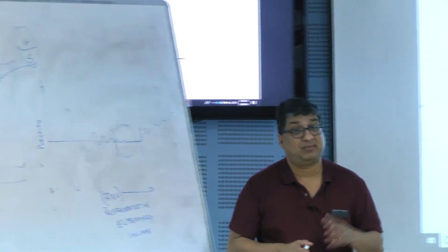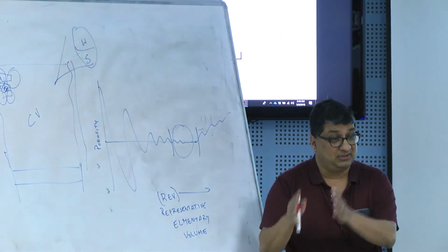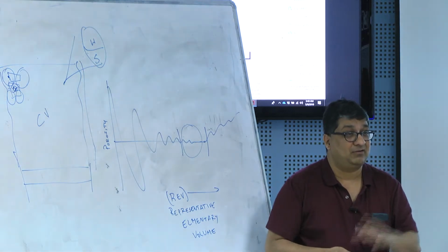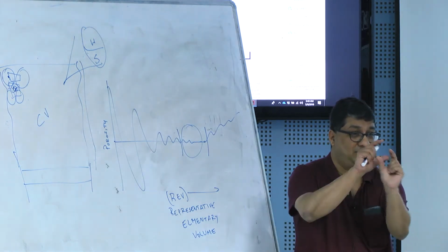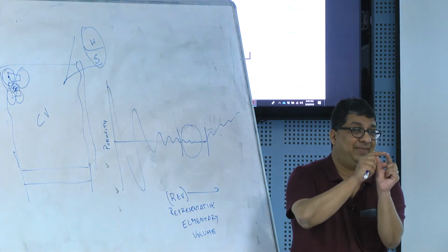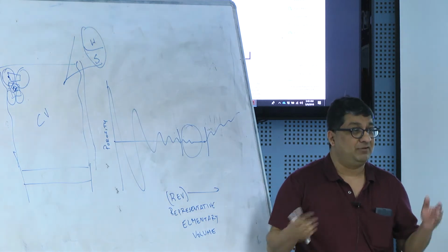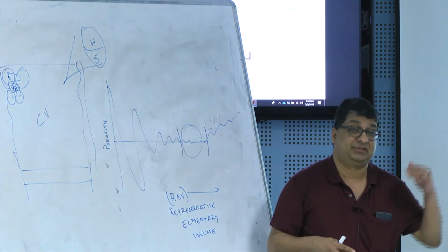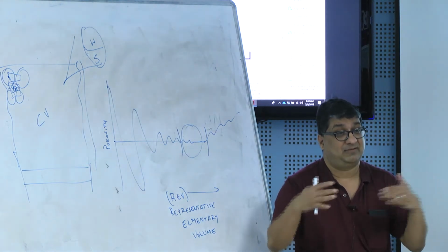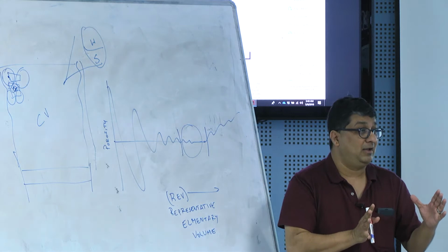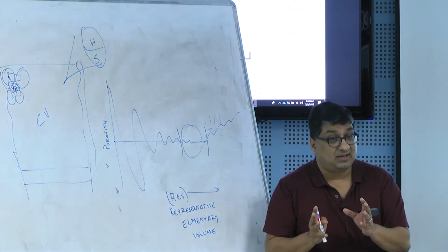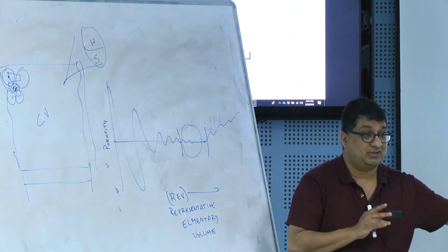Correct. So if you are doing numerical models and you want to put discrete values, the size of the cell is a measure of your REV. So the control volume when you discretize is your little control volume over which you're performing your mass balance or energy balance, and that should be the size of the REV. So if you discretize your model and say my model is 100 meters by 100 meters, you have basically said that is the representative elementary volume, the volume such that if I take a sample that size, the porosity that I measure will be representative of the porosity of the aquifer.